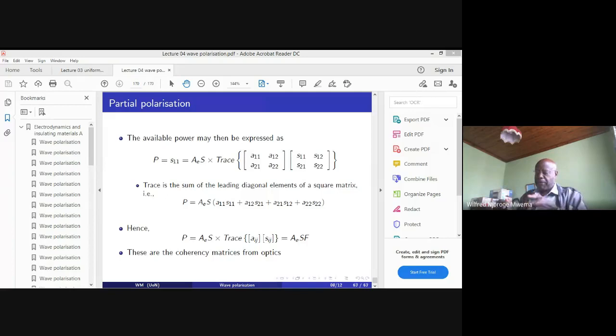Now you get the Laplacian of E plus gamma squared plus K squared multiplied by E. So gamma squared plus K squared is what we are calling Kc squared. It's a characteristic of the medium and the shape of the region the wave is propagating through. The Kc comes just because we have split the fields into axial and transverse components.